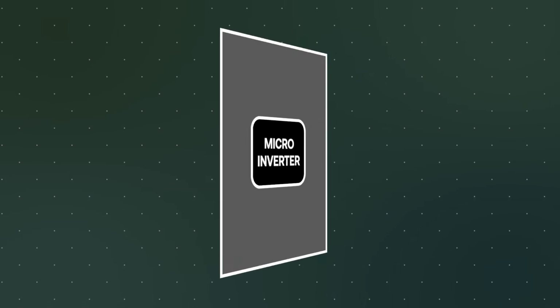In the event that the power goes out, your string inverter simply turns itself off. Now there's a smaller version of a string inverter, and this can often be referred to as a micro inverter. This is at panel level. So unlike a string inverter that's often in your attic or your garage, for example, these are places we would install one of those. A micro inverter is on the back of the panel.